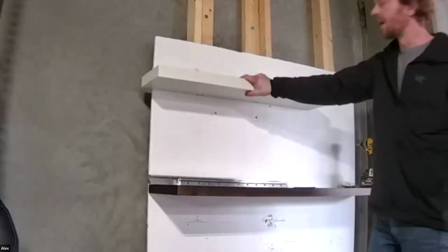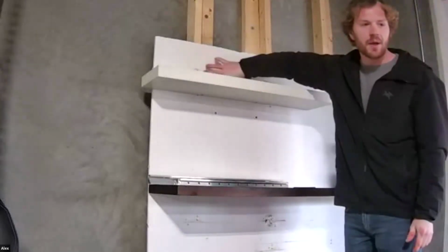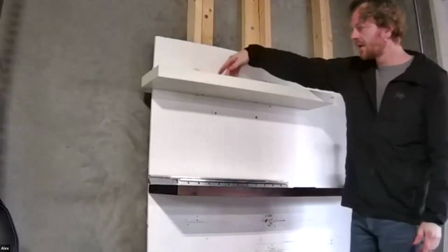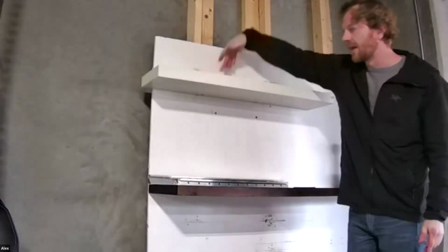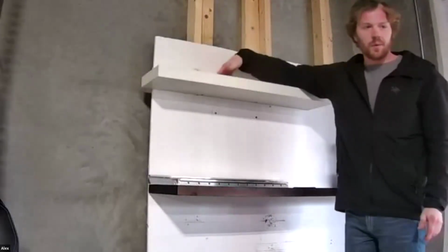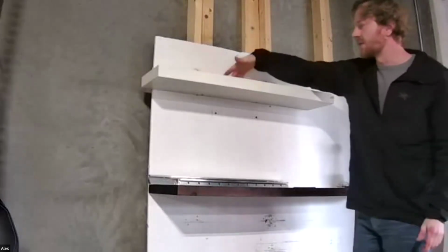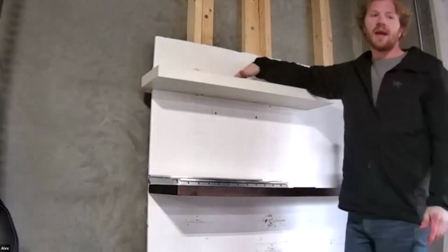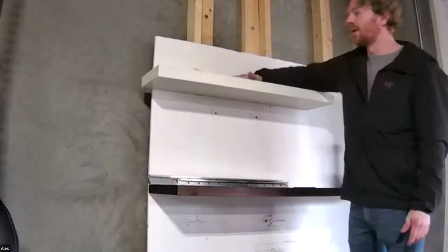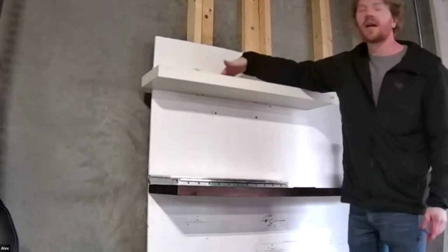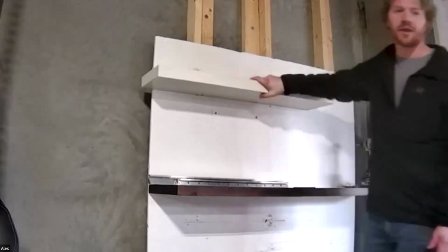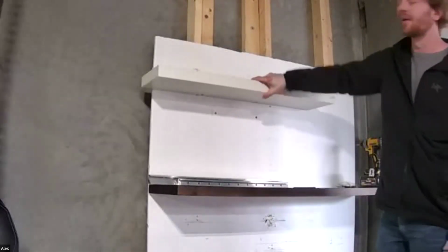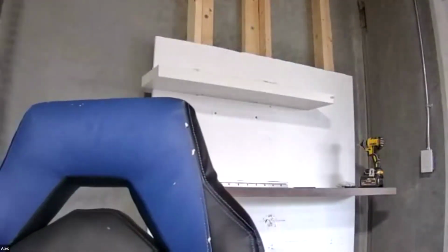And you can see, because I really tightened that male bracket to the wall, the female bracket that has that wedge here is pushing into the wall, right? And that pushing into the wall makes this whole thing sturdier. So the tighter I make this male bracket, the sturdier this is going to be. But this one's already extremely sturdy and rigid, which is how you want it.